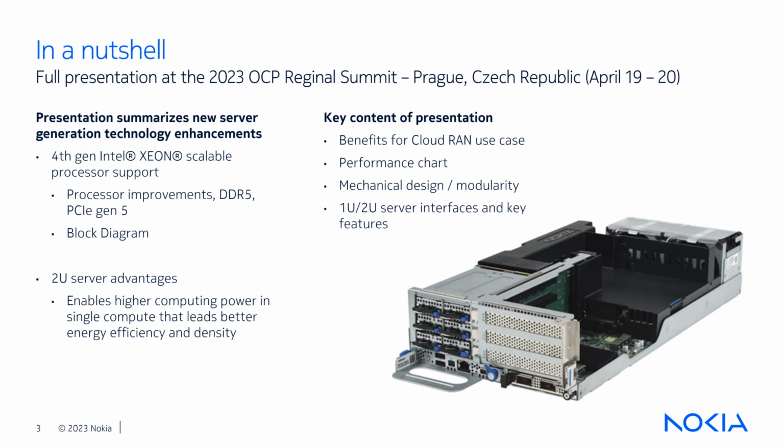Of course, we don't expect that all servers will be hosting the highest power accelerators, and actually in our key use case, where I have another presentation, we see that in this kind of 2U server, the configuration will have an OCP NIC, not that high power, 2 to 3 times Cloud Run Smart NIC, about 75 watts each, and a 185 watt CPU.